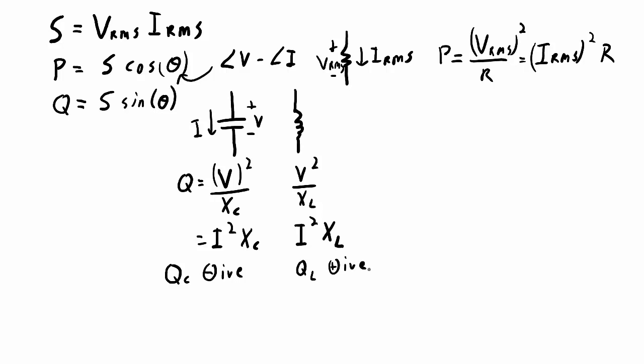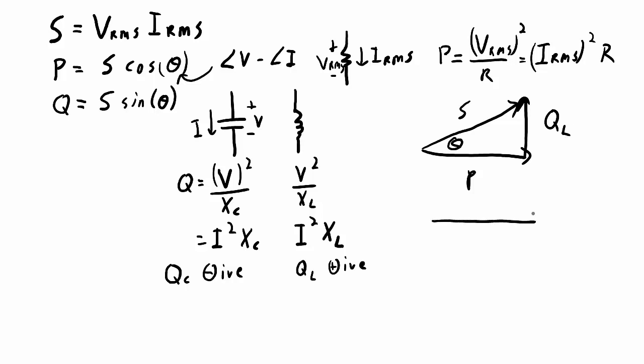And this comes from the power triangle, or the phase shifts between them. So if I have a real power and, sorry, a reactive power, I get this apparent power, and this phase shift is positive. This would occur for an inductive reactive power, whereas if I have a real power and a reactive power that's capacitive, that goes in the negative direction, and that's from a negative phase shift, where the current is leading the voltage, like it does with a capacitor, and I get the apparent power there.